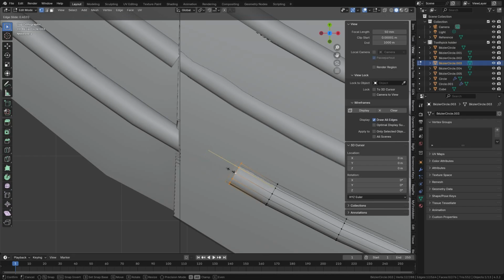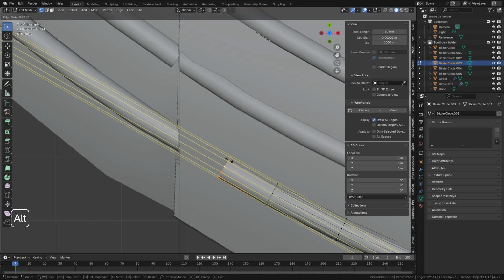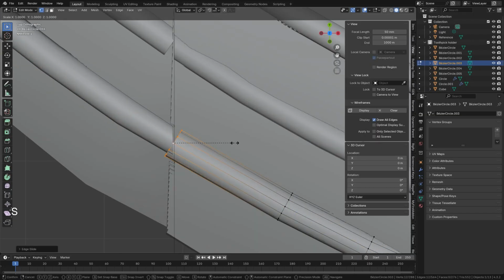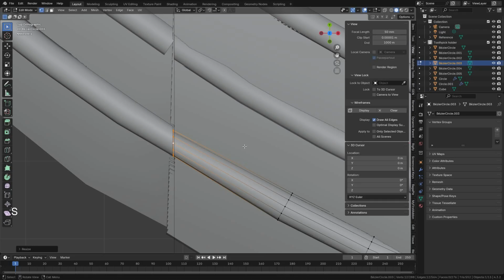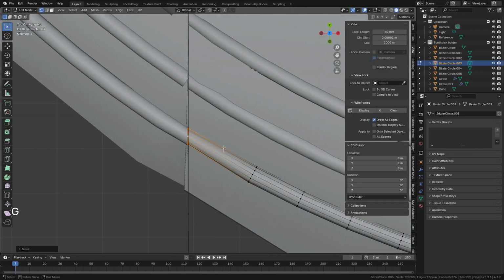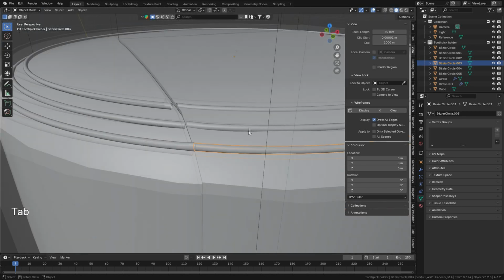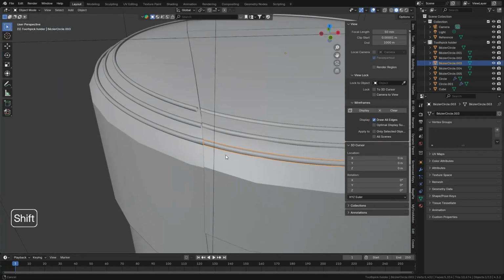You see, so now in this case, when you double tap G, you are being constrained here because you can't move further. In order to do that, you hold the Alt key whilst dragging, and then you can move further than that. That's fine. And we just do the same thing. Move them here, go back. I think that should be fine.